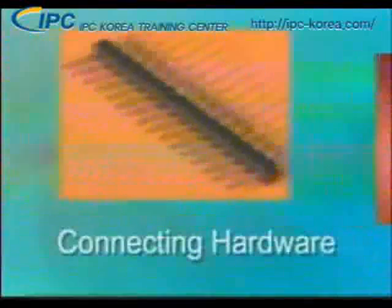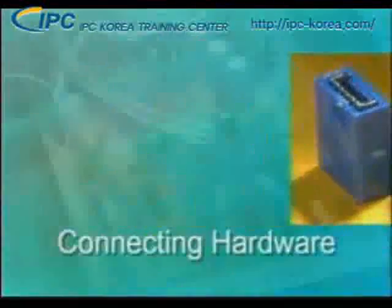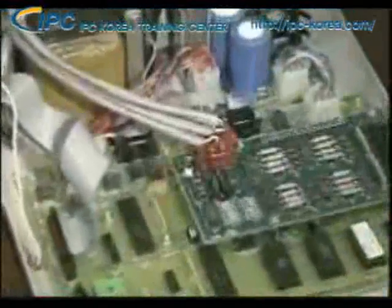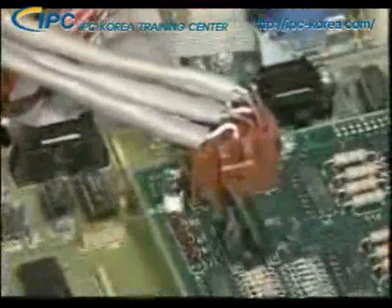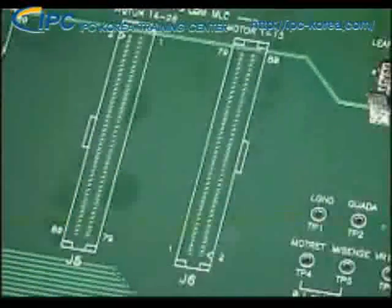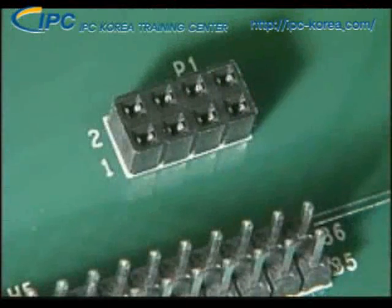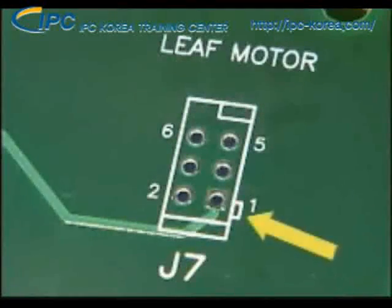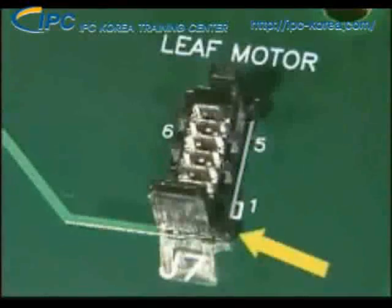This hardware is available in both through-hole and surface mount package styles. Connectors are attached to a circuit board so that wires, cables, and other outside connections can be made to the assembly. The reference designator for a connector is usually the letter J. Sometimes the letter P is used. Connectors are oriented based upon a bevel, notch, or pin number molded into the package.